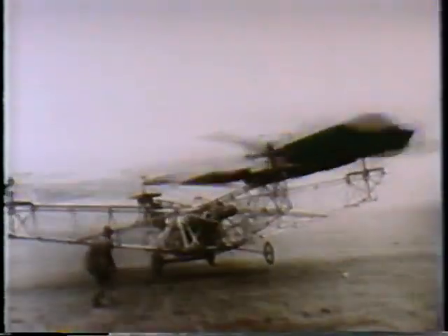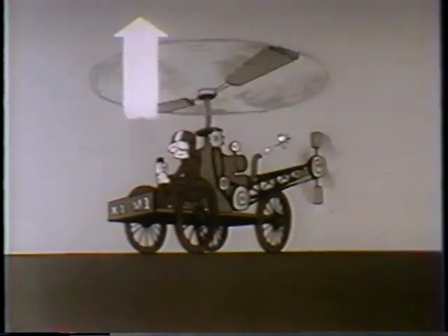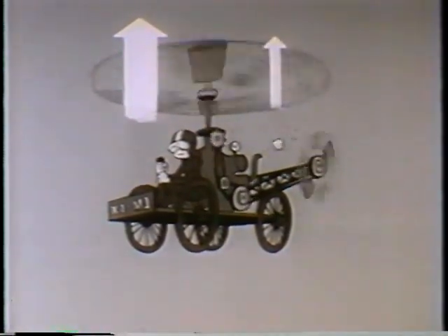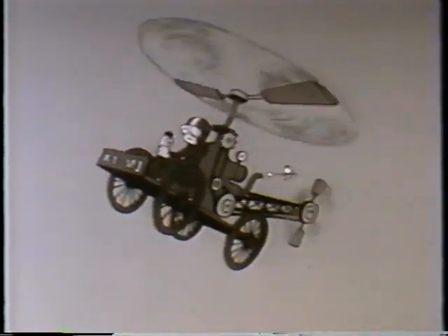One of their major problems was dissymmetry of lift, which means simply that in directional flight, rotor blades always tend to exert more lift during the advancing half of their cycle of rotation than they do during the retreating half. The result, of course, is an unfortunate tendency for a helicopter to turn over on its back.